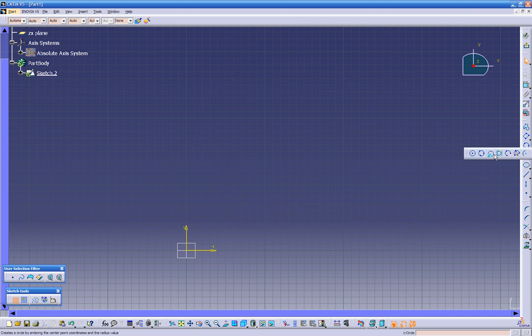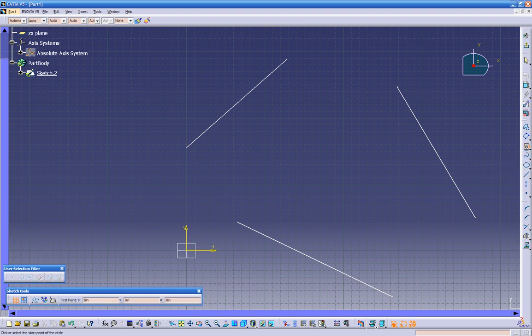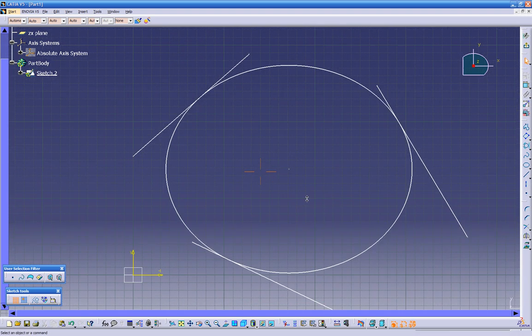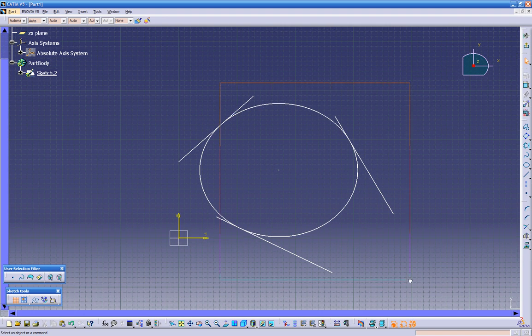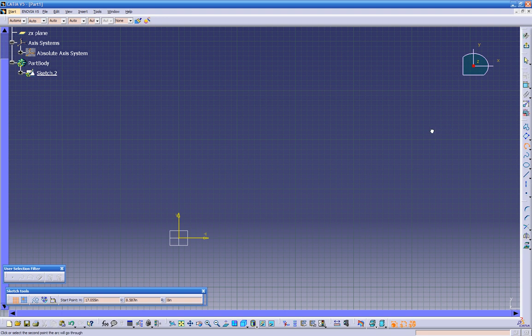Let's see what else. Coordinates, tangent with the 3 lines. So if we double click on the line, have a line here and a line here, we can click escape so we can get out of the line. Let's click on tangent, click on line number 1, 2, 3, and there's our arc, our circle. So let's delete this. We don't need this. Click on the circle and delete. So we have different options over here to create a circle.